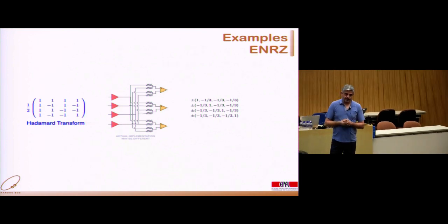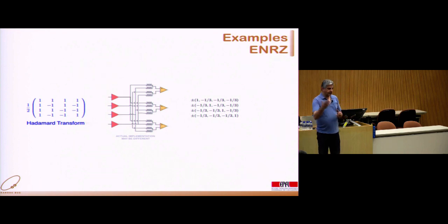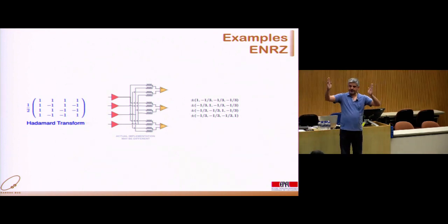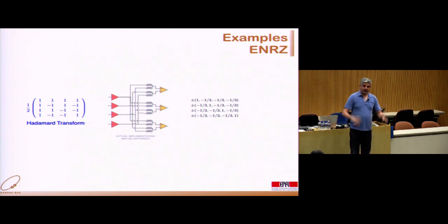The wire length is an issue. It's called skew. Absolutely. That's a very good question. The question is, if you have many wires, and they are not completely matched, does that cause a problem? It absolutely causes a problem. Especially at very high speeds, you want the wires to be matched almost perfectly.